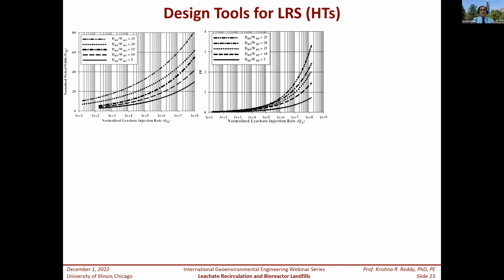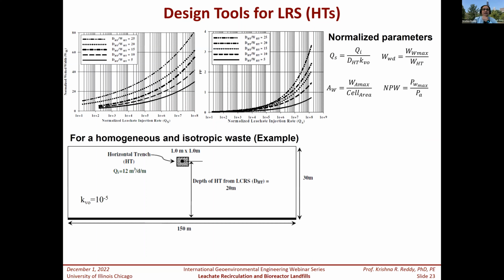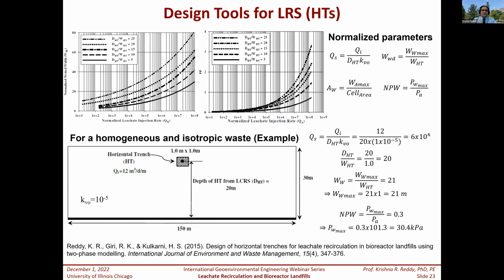So deciding this leachate recirculation system spacing and the pumping or injection pressure or injection flow rate are very critical. As I mentioned, there are no guidelines on these things. So several years ago, we did some hydraulic modeling, and then we created these design charts.